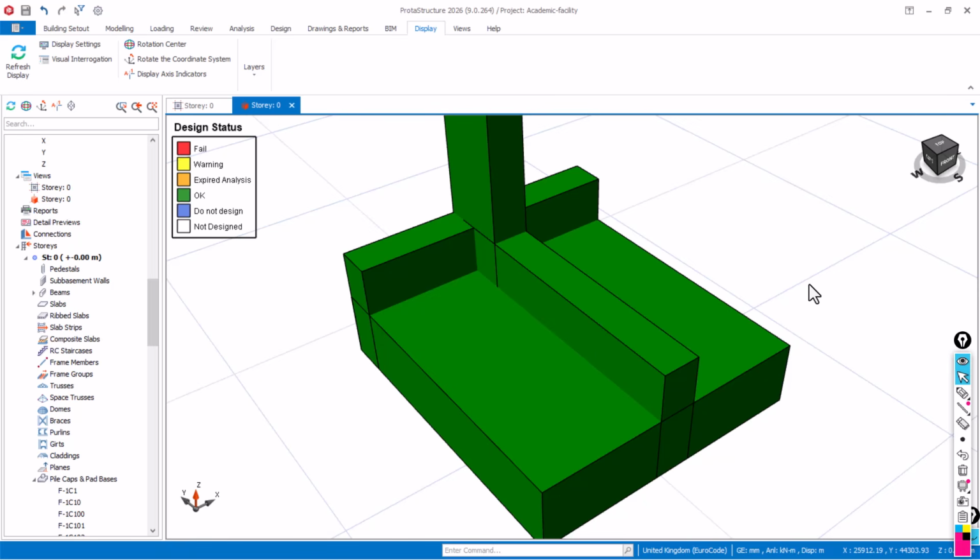But this, as you can see here, is like a cantilever beam. You understand? And this is not transferring any load anywhere. It's not transferring any moment to any footing. It is just on itself. Now it is even adding more self weight to this footing. So this is a blunder.